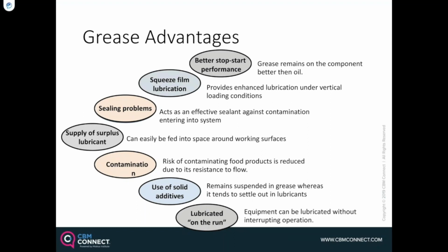It used to be very commonplace to lubricate equipment while it was operating. I don't know that we encourage that. That's got to be done, but the proper guards and safety precautions have to be taken into account. Frequently, what's happening now is the grease hose is being remounted, 2 foot away. There's a hose that goes into where the grease zert was. You put the grease zert in one end of the hose, and it's pushing the grease into there, so the safety does not create a problem. The safety concern is not an issue.